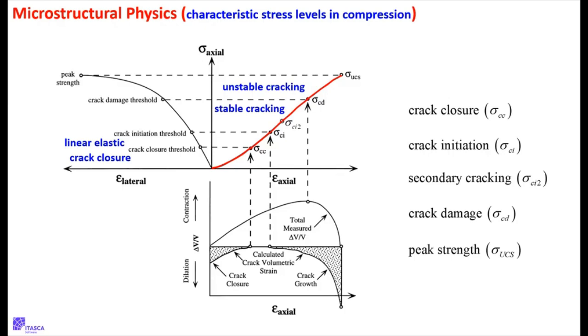We'll show you pictures of it later. This is considered to be like typical granite, okay? And so this then is a UCS test. Take that small cylinder, put it between two steel platens, put special crazy Teflon stuff that you spray on there to try to get almost zero friction.